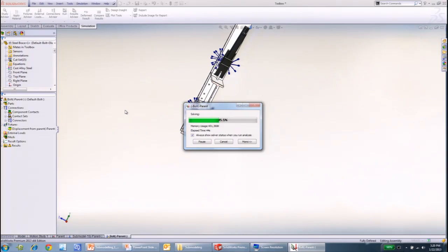Yes, there is a limitation right now. You can create these new cosmetic weld beads in SolidWorks, but when you come to simulation, they mean nothing. They don't come as solids. At least in the old workflow, you were actually creating a geometry which would work in simulation. In the new workflow, it doesn't. So we haven't fixed that. So it's still painful. You have to do an extrude, or you have to build the weld.